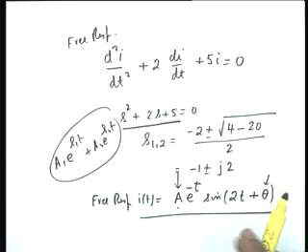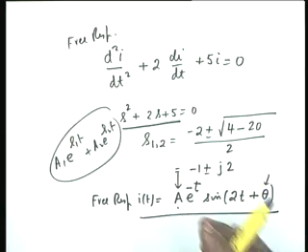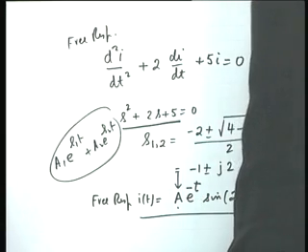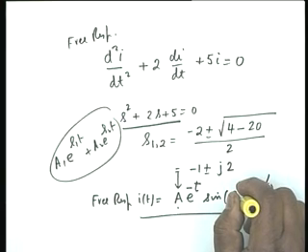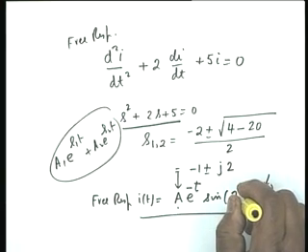Then if you want to solve this completely, what you do is you bring in the driving sources, find out the particular integral, all right, add the particular integral to the complementary function and evaluate the constants from the initial conditions. We have solved this kind of a circuit earlier. Okay. Is the point clear? What this question wants was only the form of the free response.